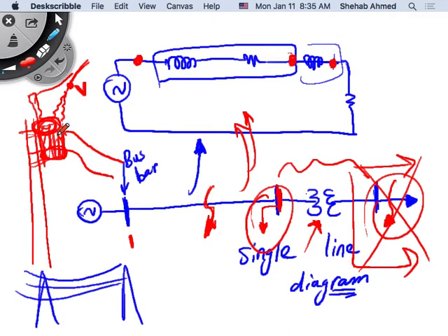So definitely you don't want to bring a conducting terminal close to something at a very different potential because of the potential of the arc. So these bushings are insulators that protect against arcs occurring. So you need to keep some distance.